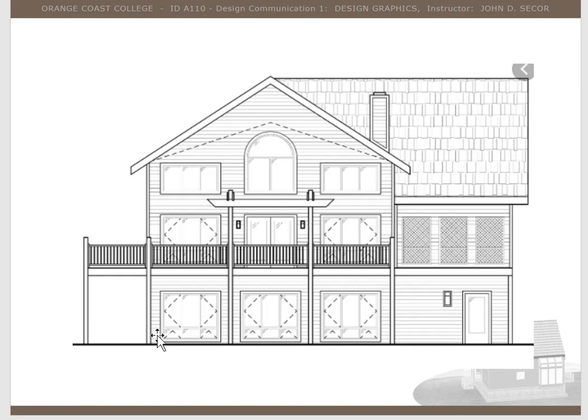They have lower windows and upper windows. So this is a whole window wall right here. Now these hinges, see these little triangles with this little dashed line? We talked about dashed lines. These little dashed lines indicate which way the windows swing open. So these swing open, they're connected right here. Down here, you'll see the dashed line pointing in a V. So these swing out to give lower window ventilation. Here again, you see the hinges of where the doors open. They also added details like little diagonal lines to represent glass.